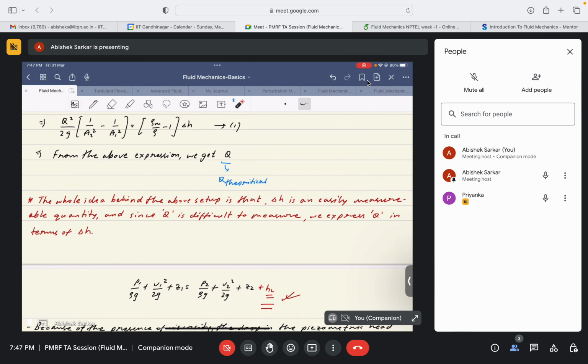No, it won't be less. It would be the same. The thing that matters is how you're pushing the water from the inlet to the exit. You need some energy to push the flow from the inlet to the outlet. Since you want the same mass flow rate at the exit, you apply some additional energy in terms of a pressure gradient that overcomes these viscous losses, so that the flow can be pushed from the inlet to the outlet. The mass flow rate never changes. The mass flow rate would remain same.